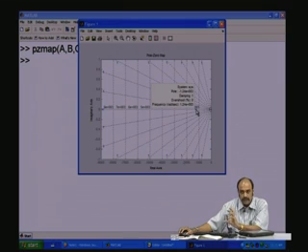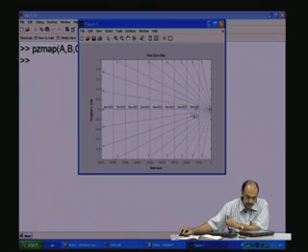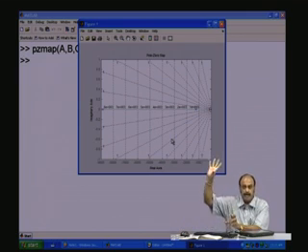So, which means there are now some oscillations which are going to occur between the capacitance and the inductor. It is now going to act more and more like a resonant tank. That is, when R2 becomes totally open circuit, it is just pure LC, because R is just 1 ohm. So, it is an LC tank, and therefore, it will start oscillating more and more. So, which means these poles will start moving up and below. So, you will have one pole here and one pole here, and they will start moving towards the imaginary axis more and more as you make R2 higher and higher.